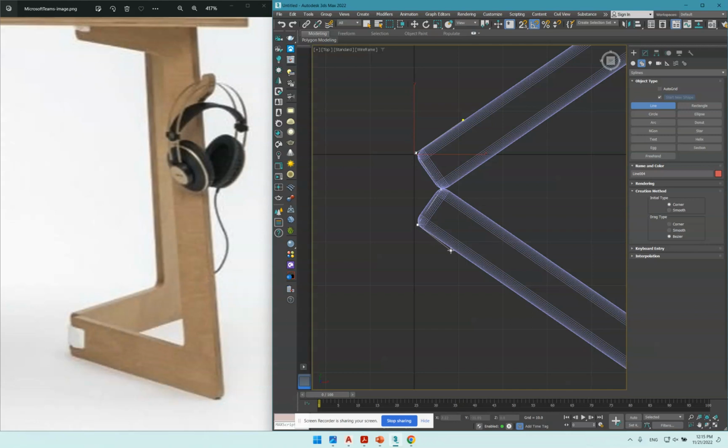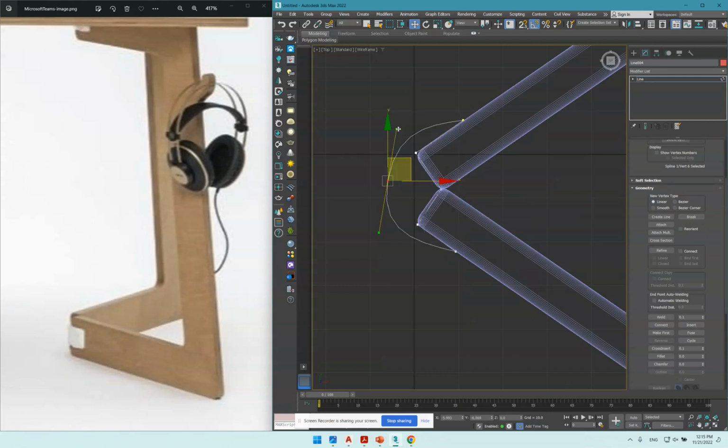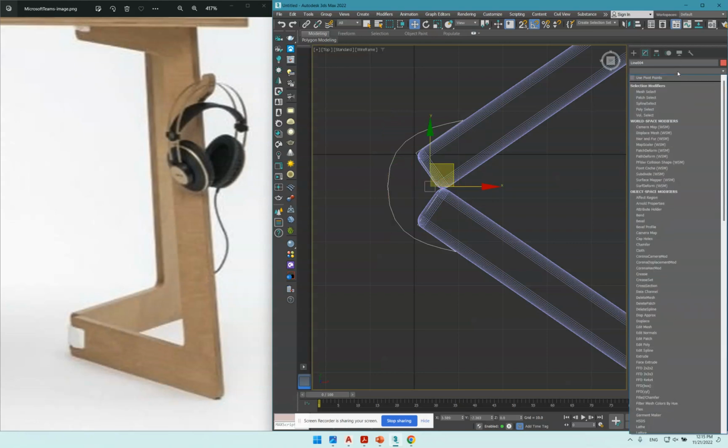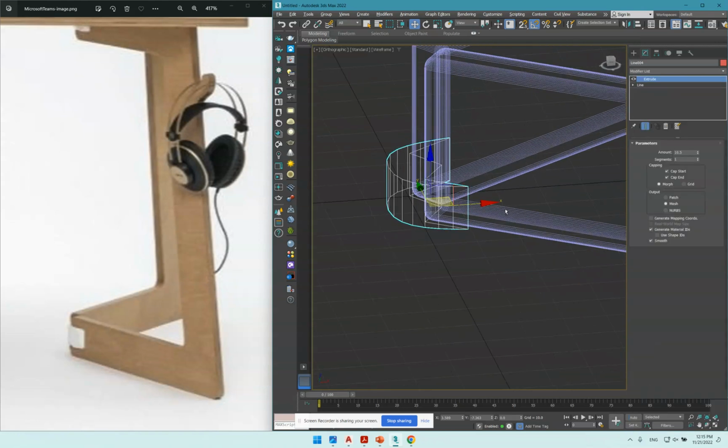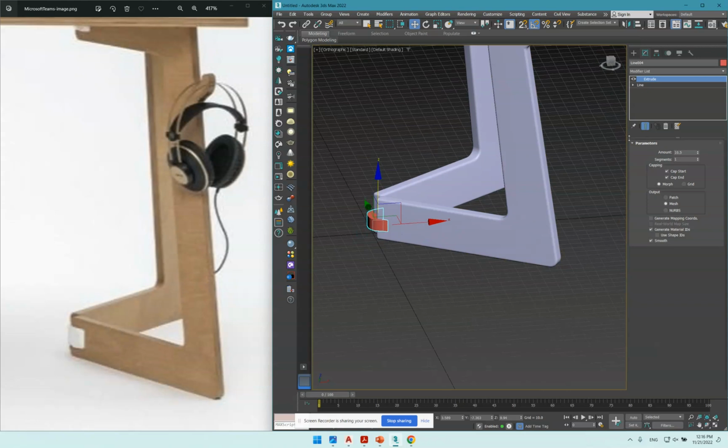For now, I'll just create it, or you can create for one side only and then you can do the other one. So for here, for example, I will create a curve and then close it. Yes. Go to vertex and start adjusting everything. So I will move it this way, and maybe I'll move it a little bit to this side, and so on. When you are done editing everything, you can again extrude it according to the height that you want, and you can move it up and down.